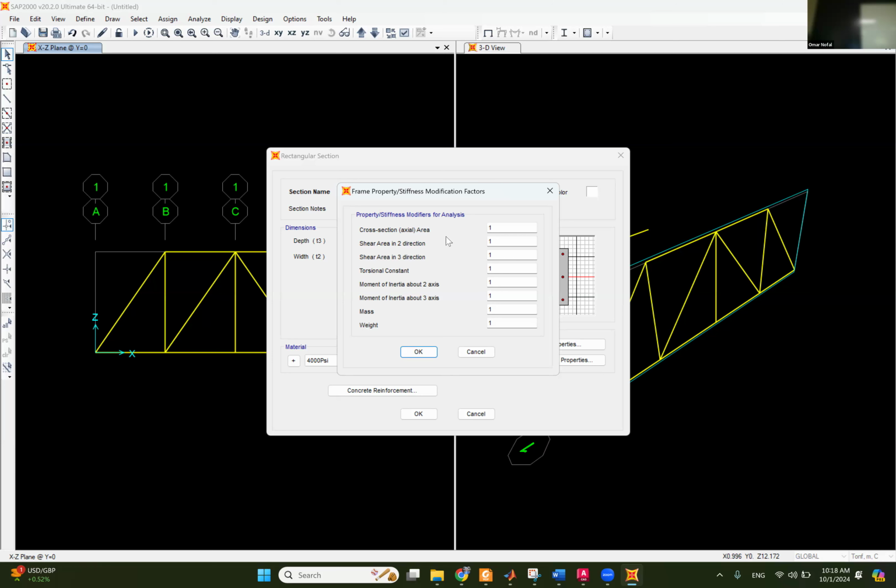Sometimes it's going to be 0.5. It depends on the element and depends on what hazard that we are dealing with. Okay. So sometimes the stiffness that we're dealing with is 100%, but also there's other applications. Sometimes you do forensic analysis for structures that already have been built for 50 years and the sections are deteriorated. So when we model them in SAP 2000, the stiffness sometimes is not 100%. Yeah, the cross section is 1 meter by 1 meter, but it's cracked from different places. So maybe you need to reduce the stiffness of the elements if the structure is deteriorated.